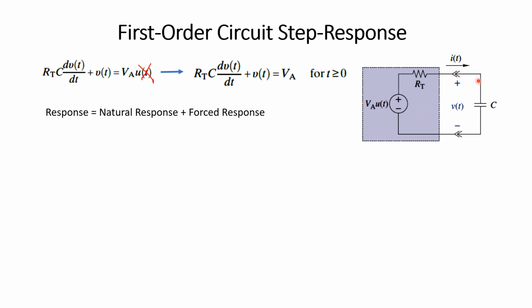And in this, we will be finding capacitor voltage, because it is a state variable. First, we will find capacitor voltage, and then due to the capacitor voltage, we will find current, because current is C dV by dt. Knowing the current, the current over here is also the same, and we can find the voltage over here. So here voltage and current are known, this is the source, and it completes our analysis.